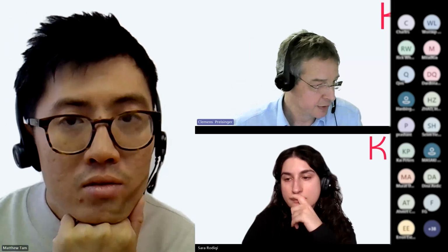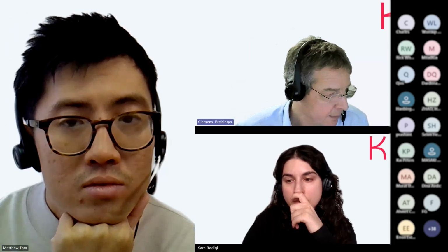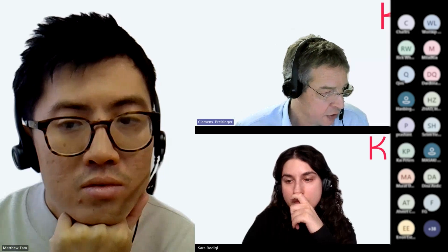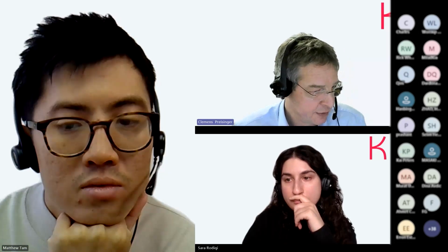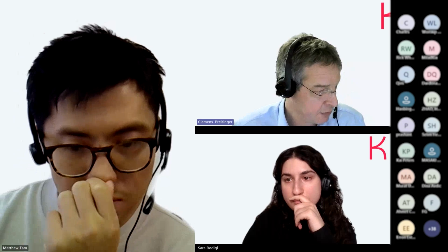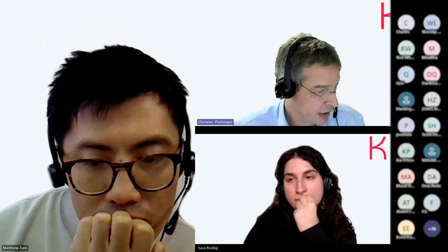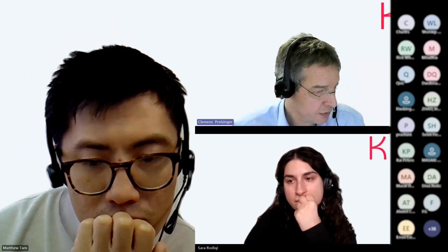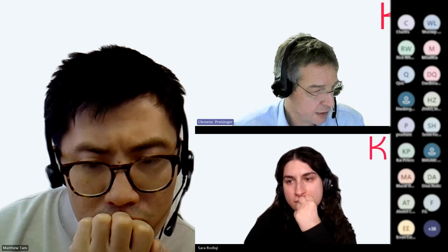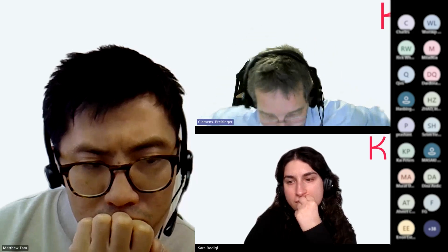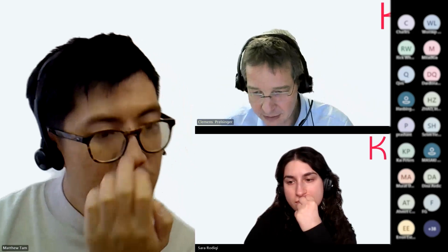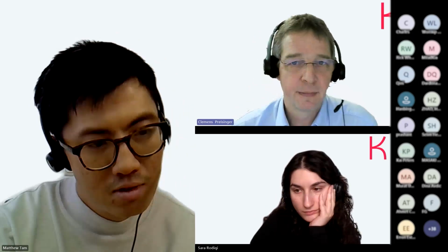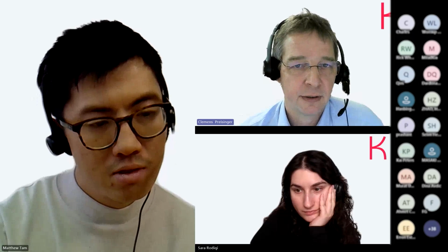There's another good question. What is the actual logic behind large deformation analysis? Is it containing dynamic relaxation? I'm wondering if I can do grid shell optimization with that. Any tips? Yeah, at the moment there's this one large deformation component here, which is used for form finding.